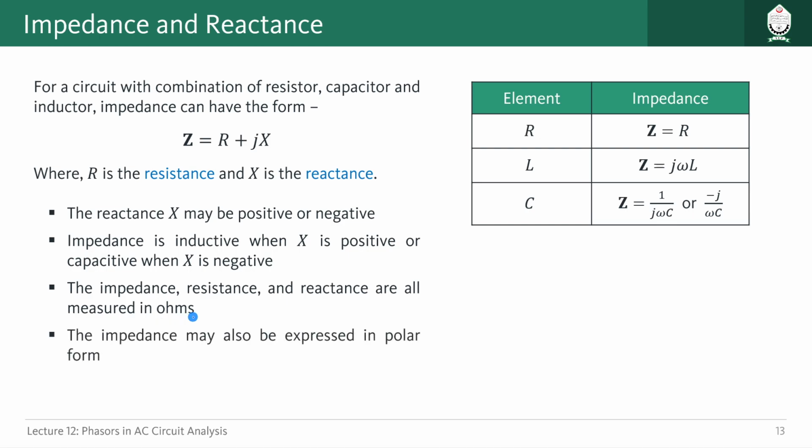And finally, for simplification, we can also represent that in terms of its polar form, something like this. This is also possible. Whenever we need it in our circuit analysis, we can represent the impedance in its rectangular form or its polar form, no problem. But finally, when we get the results, the voltage or current quantities have to be written in terms of their time domain version. That is the only requirement we have here.